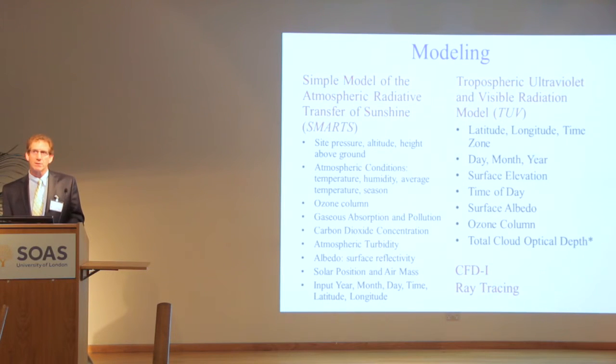And there are other models that we use very conventionally for design of so-called conventional UV disinfection systems. What we want to do is adapt, for example, computational fluid dynamics and irradiance field modeling, that's this thing down here, and ray tracing for purposes of simulating the performance of these systems so that we can optimize their performance and design a better widget. So these are being used for reactor design and optimization, and we're really adapting this from approaches that we've used with conventional systems.